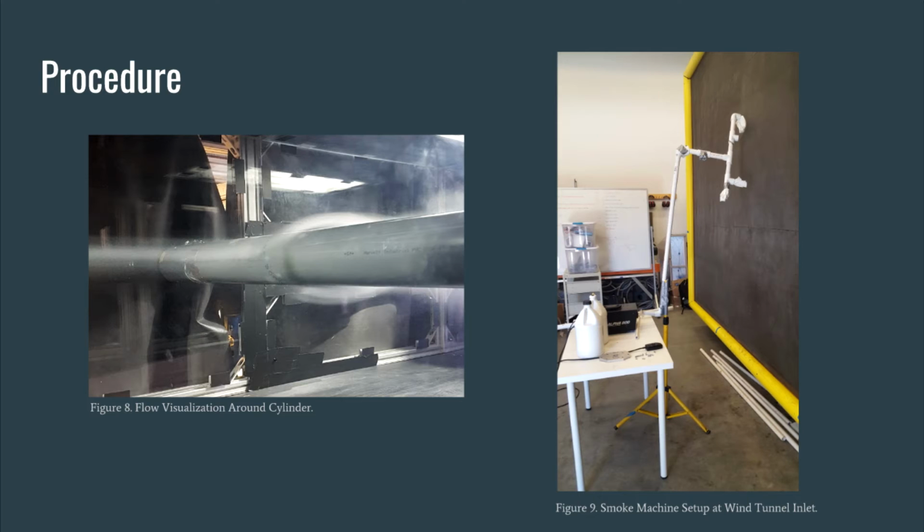The wind tunnel was then turned off so that the boundary layer tripwire could be attached to the cylinder as previously indicated. Ensuring that it was properly secured, both pressure data collection and flow visualization were once again completed at 100 and 600 RPM. Once all necessary data was collected, the wind tunnel speed was reduced to 0 RPM and the tunnel was turned off. Final wind-off pressure readings were taken and the experiment was complete.